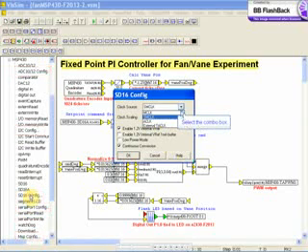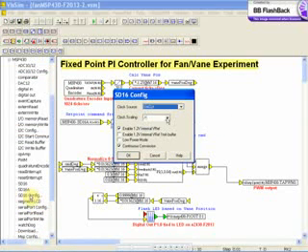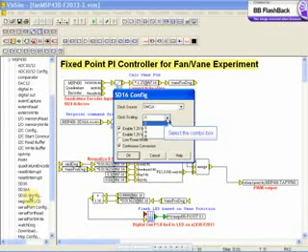For the Sigma Delta configuration, you can select your clock source here, as well as the scaling or divider. Enable the internal voltage reference here, as well as enable the reference voltage available on a pin here. The MSP part specification will let you know which pin.